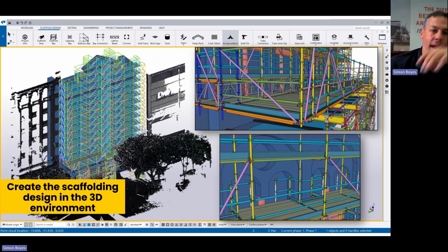Also, with being able to crane all those beams and everything in, there's some quite critical lifts there and making sure all the alignments and everything's correct. So you can actually eliminate a lot of the risks in the project purely through the collaboration before the job starts. So look, as designers and scaffold managers or supervisors or whoever's running the job, we've got an obligation to make sure that we design out as many risks as possible before the job starts. And this is just a great example of that.